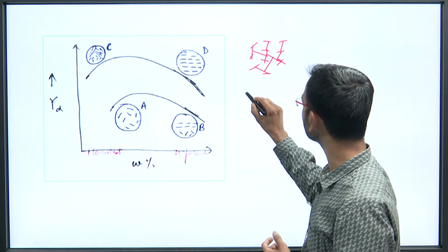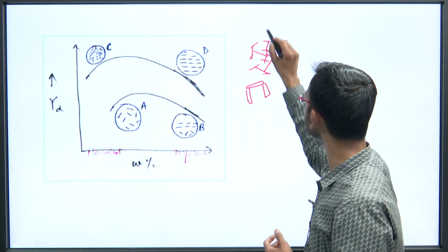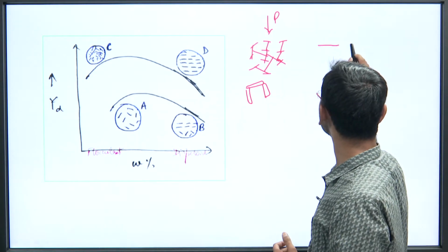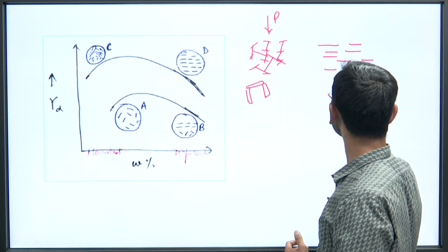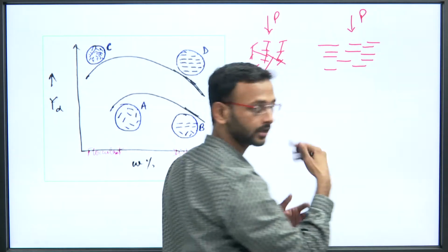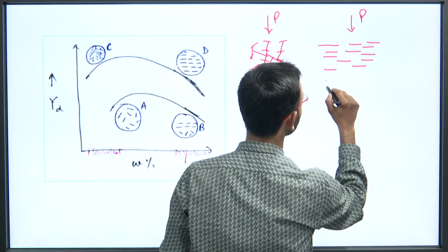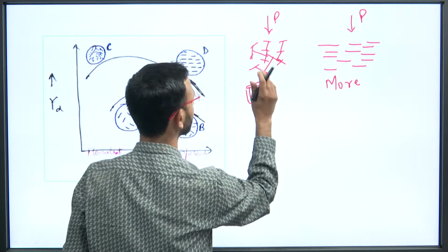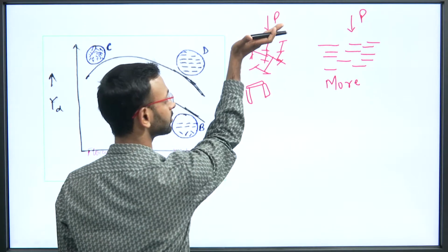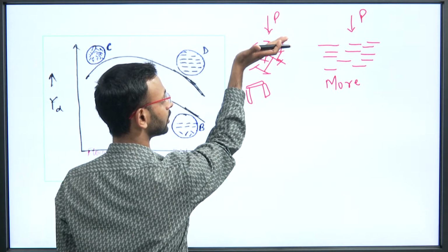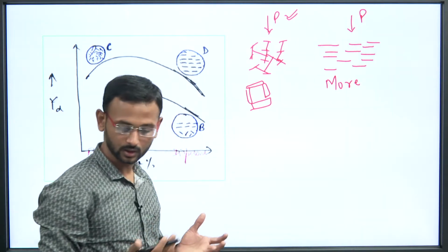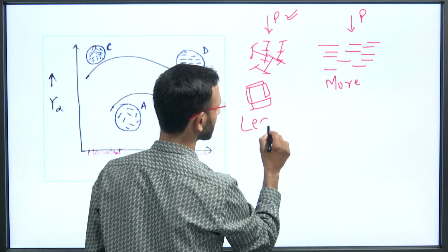When this kind of structure is there, what happens? There is some reactive restraint that is available. Let us say if some load is applied here, what happens? This structure will try to resist the load. But if the structure is like this dispersed structure, that we have already studied and discussed when we talk about the clay structure, then if the load is applied here, the shrinkage which will be observed will be more. But here, because of the reactive restraints, when the force is applied, this structure will not try to collapse at first, and then this structure will put a reaction above for this load, and so due to the reactive restraints available in the soil, the shrinkage which will be observed will be much lesser.